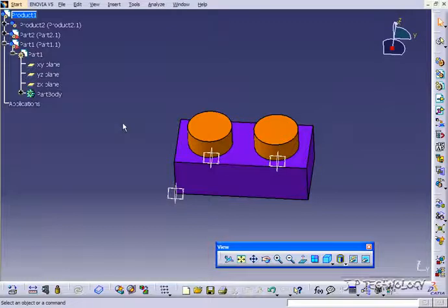Now the reason why, if you hide the part body compared to just hiding the part that's put into the assembly, is that the part body is the whole part. So between all of these cylinders, all of their bodies will be hidden. Now if you just say that part 1 is going to be hidden, it's just going to be this one guy compared to cylinder 1, cylinder 2. So on a lower level, as you're hiding them all, it's going to hide across every single instance of that part that's in your assembly.